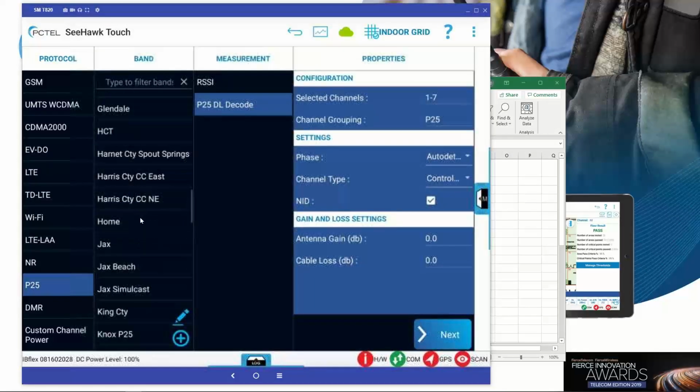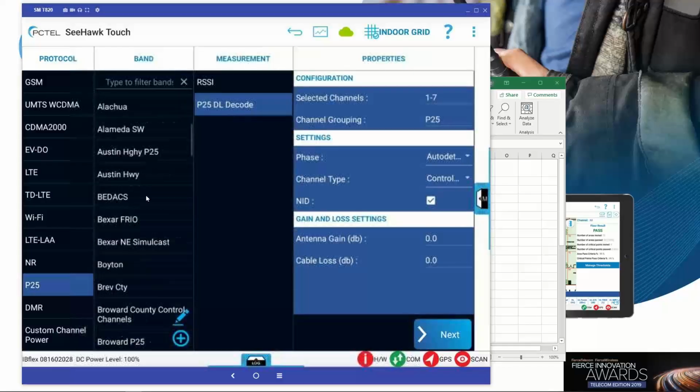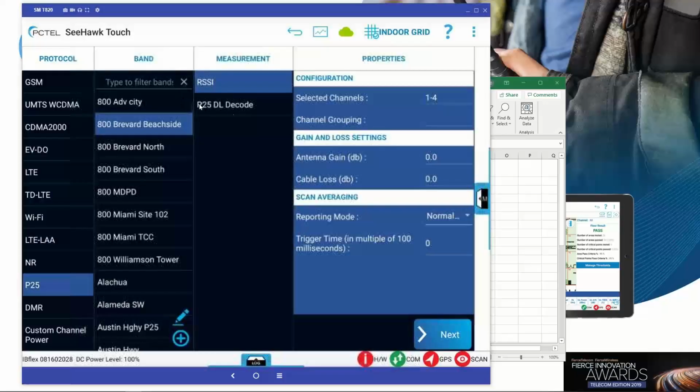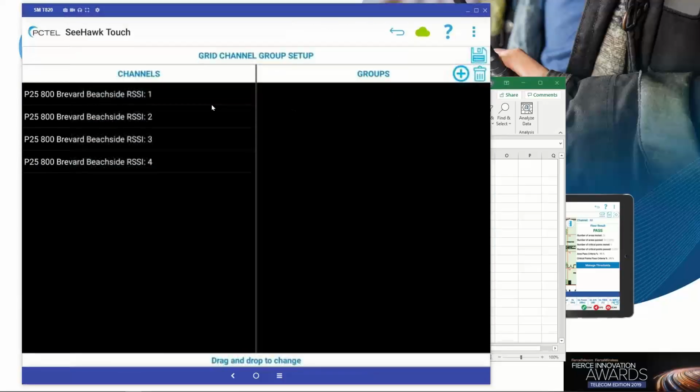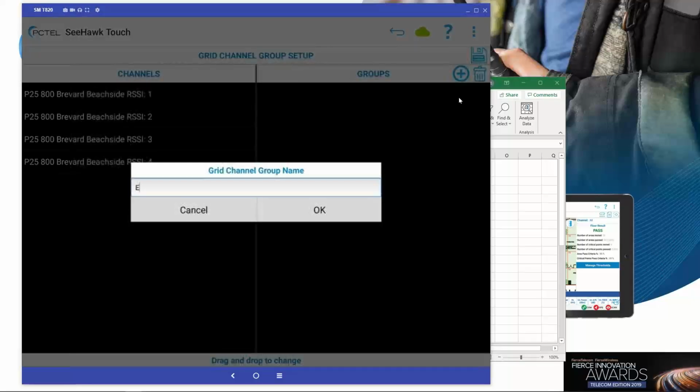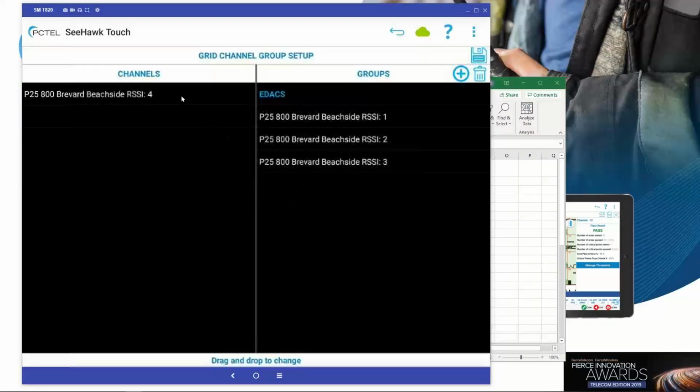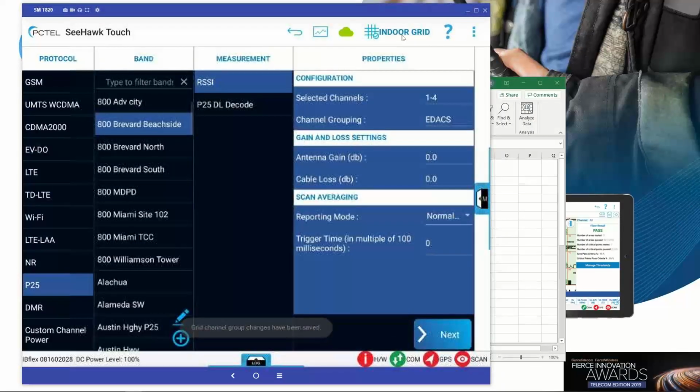I have a question for you while you're setting up your group. Can you export any of this out to something like MATLAB if you have to do more detailed engineering work, post-processing? Yeah, you can. When you downloaded the software, one of the things you got in there was something called an auto export utility. That auto export utility will create a CSV file. Okay, perfect. I just wanted to make sure because Joe will probably have more need for that when he's doing modeling in the future, especially if they have to do proposals and things.